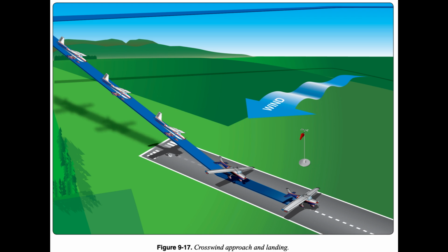Flaps are used during most approaches since they tend to have a stabilizing effect on the airplane. The degree to which flaps are extended varies with the airplane's handling characteristics, as well as the wind velocity.